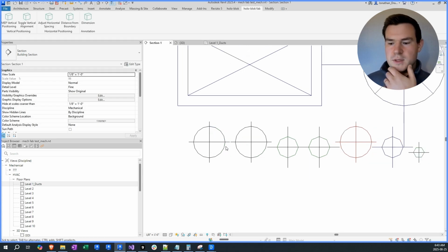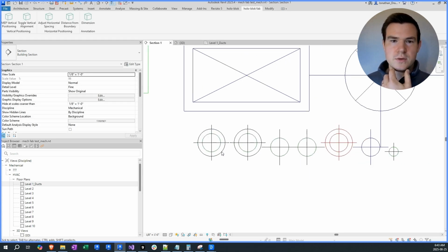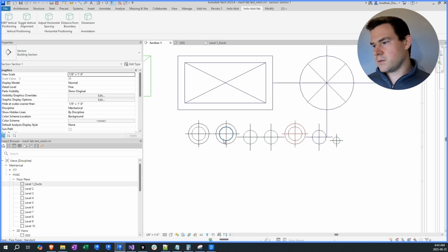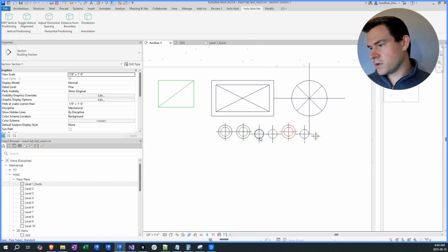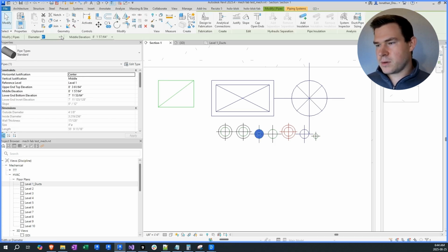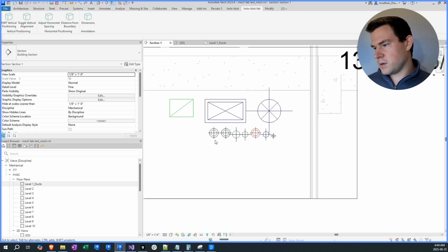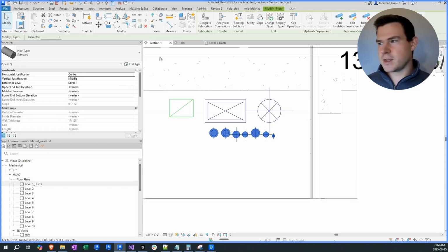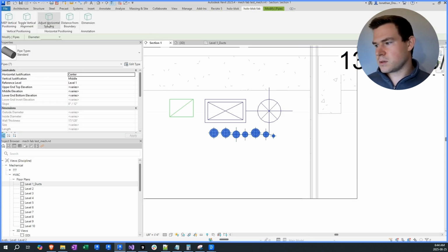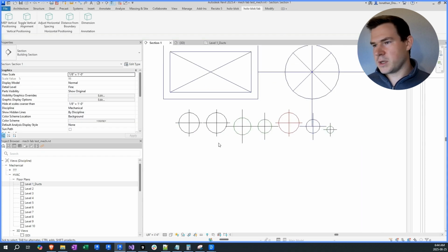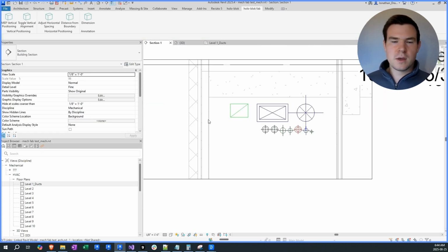And the nice thing about this is it also takes into account that insulation value. If anything changed for some reason, like a pipe changed in size, we don't need to spend a bunch of time fiddling with things to get the spacing right. We can just click on that again, and that spacing will update to what we want it to be.